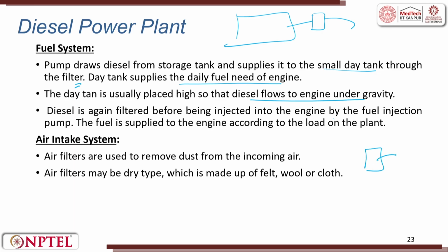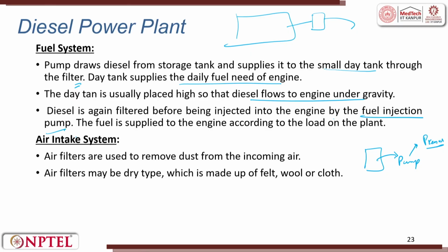This fluid will be pumped to increase the pressure. That is done by the fuel injector pump, right. So, larger tank, smaller tank, then you have an engine on one side. There has to be pressurized diesel which is to be injected. So, you will have a fuel injection pump. The fuel is supplied to the engine according to the load of the plant.